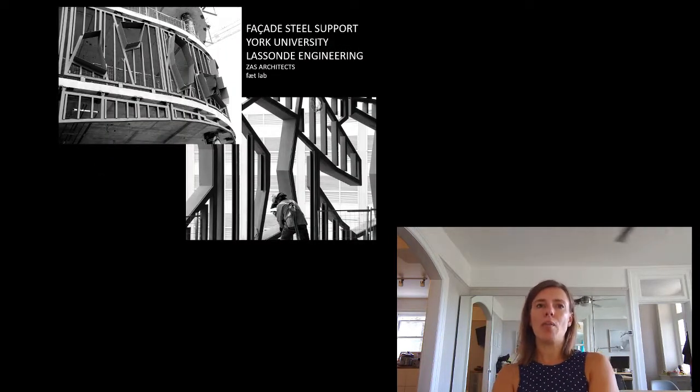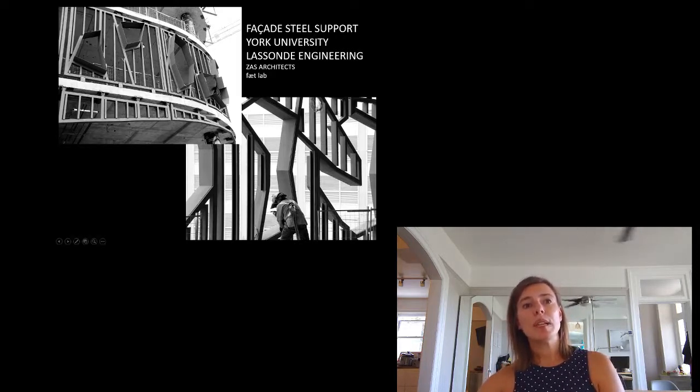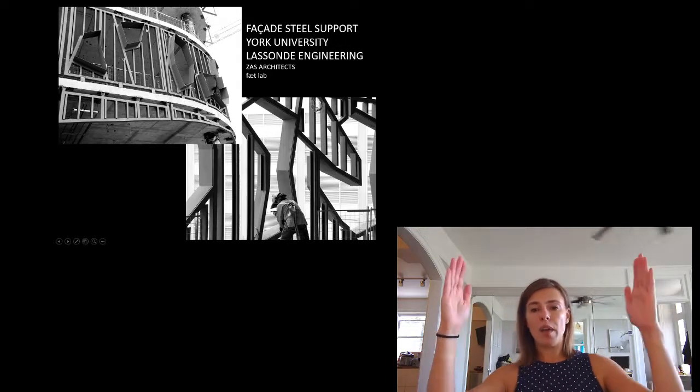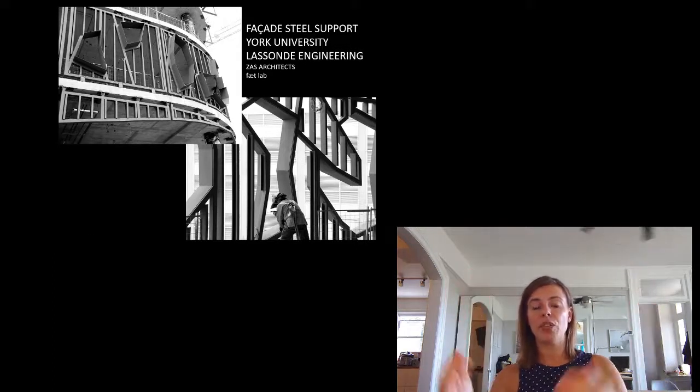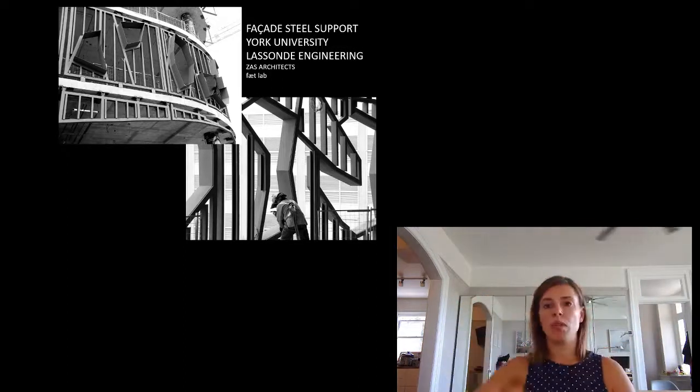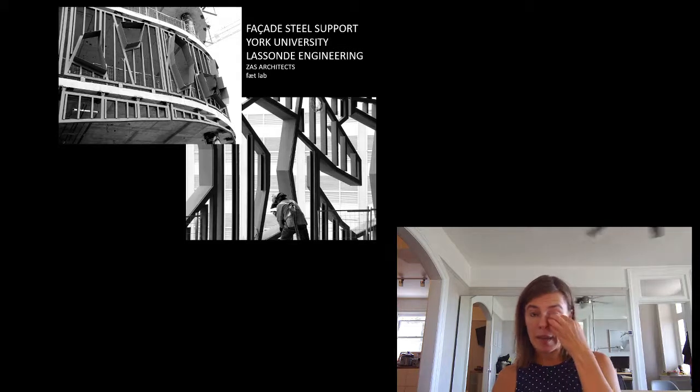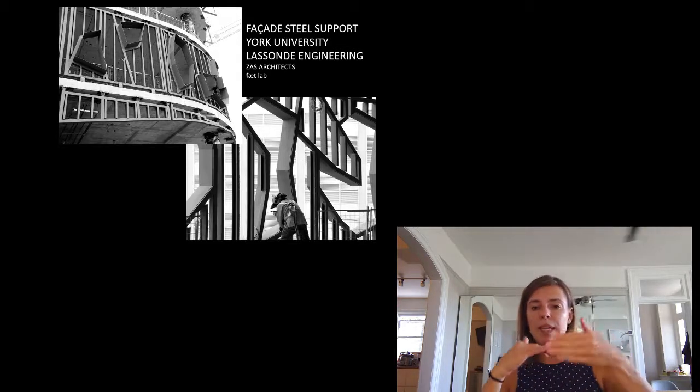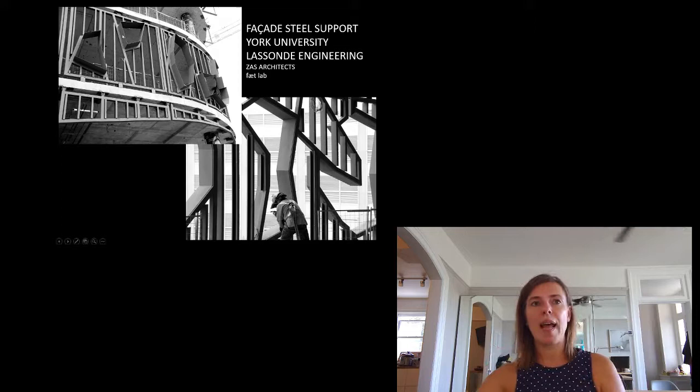Again, getting into more complex 3D geometry. This is the Lasalle School for Engineering, where I didn't do the base building, but I did do the facade support. What was interesting about this is the facade was out half a meter from the edge of the concrete slab. If you're trying to hang something off the edge of something, it wants to drop down. So we needed some way to pick that up. The facade people said, not a problem, we can stack out Z-girts and make that happen, but the windows were really difficult. The facade couldn't support the windows, so they needed their own support.